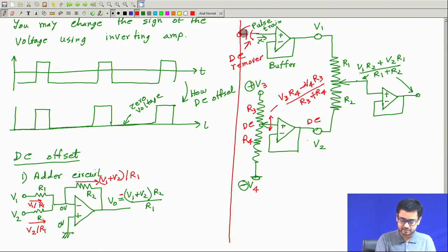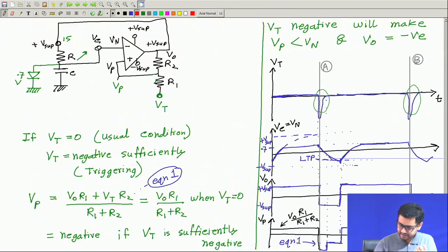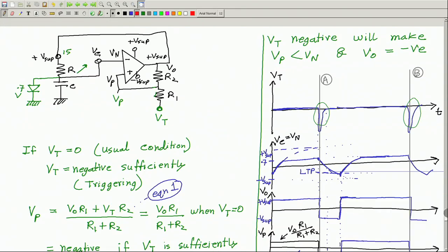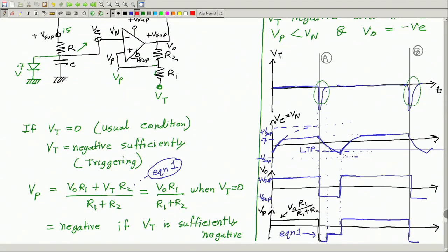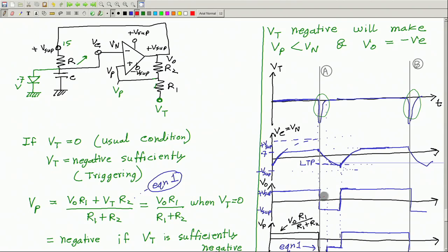Okay. So, you know that a capacitor won't allow a DC signal or low frequency signals to flow, it will allow only the high frequency signals. So, the proper value of the capacitor is to be chosen, that is another thing. Okay. Now, the last thing that we may discuss is, let us take a small example problem. So, in this circuit, how much is the duration of the pulse? So, this is called the pulse width.